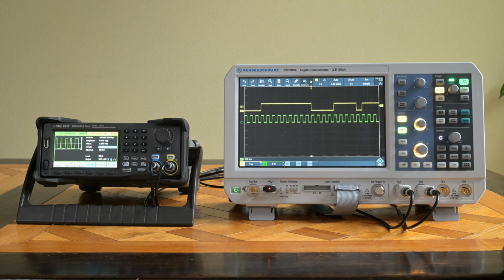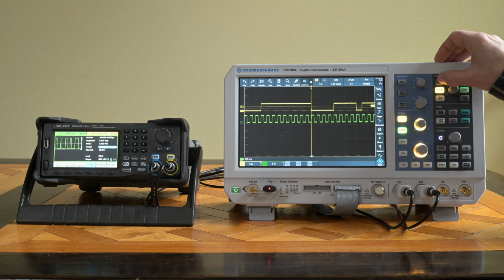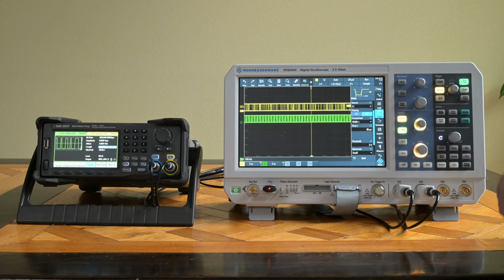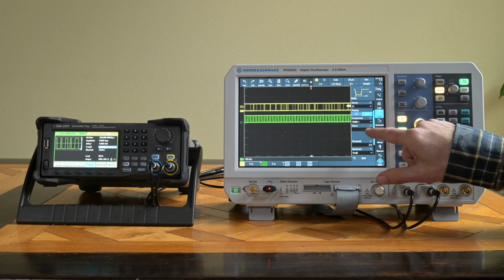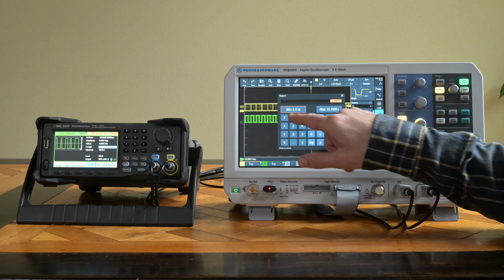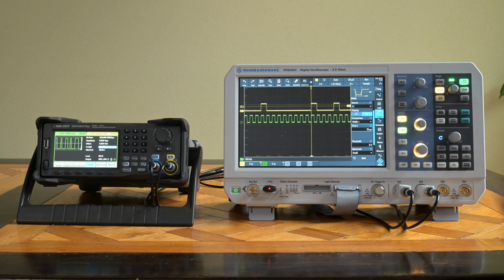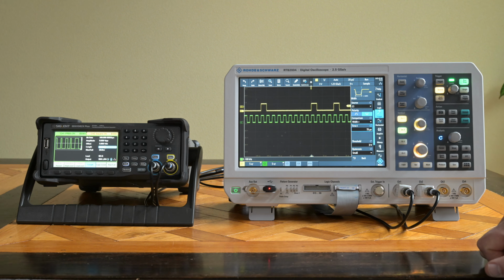I also know that it should have 8 zeros in a row. So let's also test for that. That's fairly easy as well. I will go back to the trigger and just try it for a negative trigger. It's not triggering here because there's not 9 in a row, but if I want to test for 8, I have to put it slightly below 8, so 75 microseconds. Yeah, I got 8 zeros in a row. So far everything looks good. There's nothing suspicious about this signal.